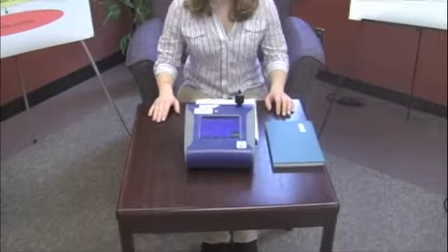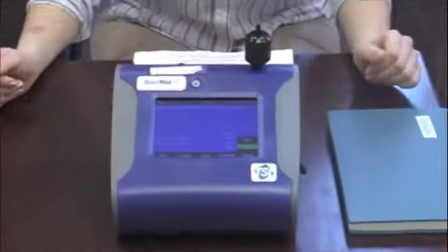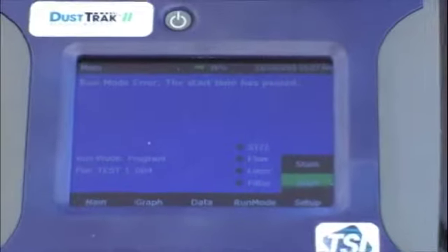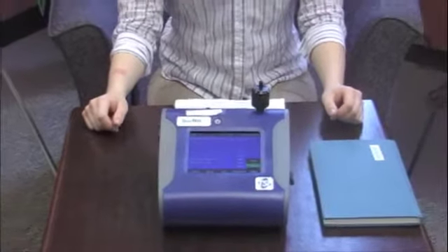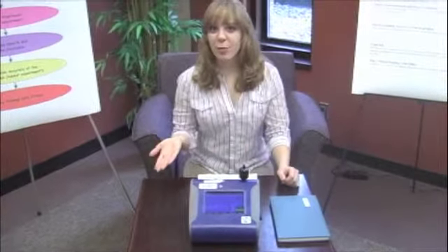Okay, now we're ready to test the hypothesis. The air quality data I gathered, and that I'll be sharing with you, was collected using the DustTrak aerosol monitor. The DustTrak is a real-time portable particulate matter concentration monitor, which measures particulate matter in micrograms per cubic meter. The DustTrak pulls in air through a small nozzle and then records the concentration of the particulates. The monitor has logging capabilities, and its calculations are a reliable exposure assessment of the particulate matter concentrations corresponding to respirable sizes of 10, 2.5, and 1.0 microns, or PM10, PM2.5, and PM1.0.